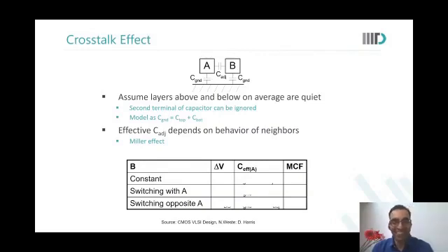Then there will be other constraints which could come because of the total current that this RC network has to drive. For example, if it's a very huge capacitance and you're talking of driving it every clock cycle, then if a current has to flow in every cycle, I have to be careful that even after some aging and some degradation in resistances, my system will work fine. So then you may want to put 7 contacts instead of 5. So there are rules for that also. There are rules linked to electromigration also. So don't worry. These are slightly advanced topics. We will possibly talk about these failure modes in the last lecture of this course.